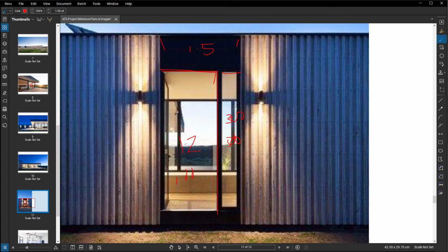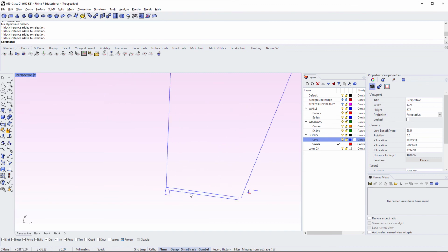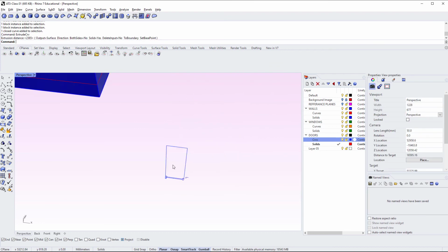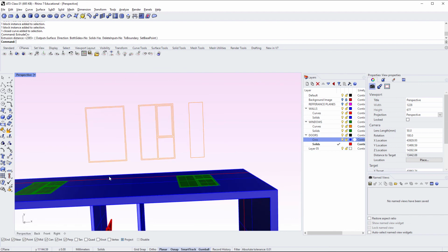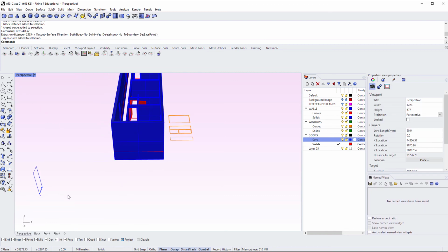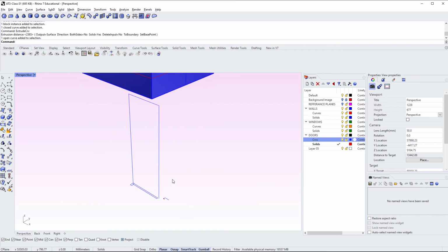And then in terms of the door itself, the door leaf, in this case it's a glass door leaf. The only difference there would be is you would draw that door as if it was a window, essentially. So instead of using a door frame like this that's just extruded upwards like we did before, what you could do is draw your door leaf on the ground like this, and then use the same method we use for glass, and then just rotate it, turn it up, and then stick it into position. There's quite a lot of freedom that you can use here, and really it's just your imagination and using those same tools in terms of the design you want to use.